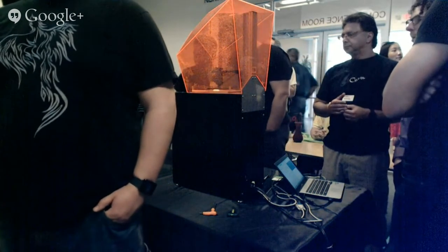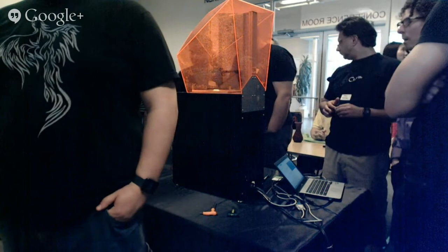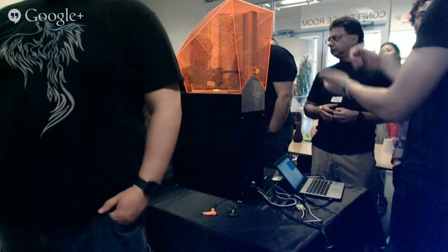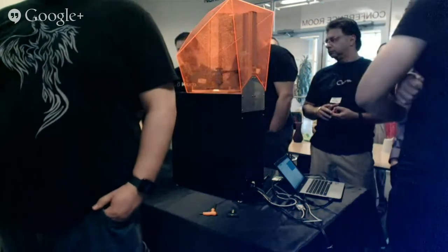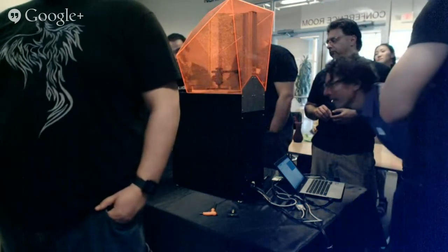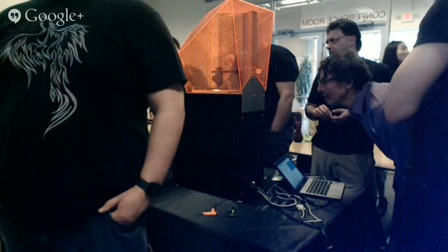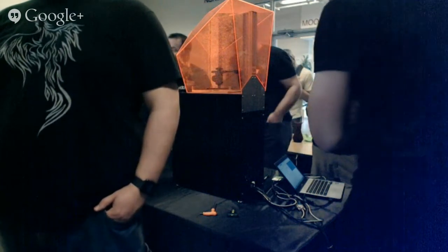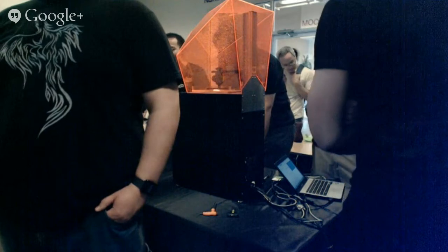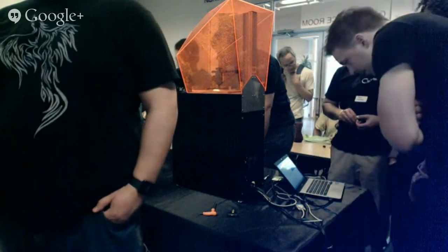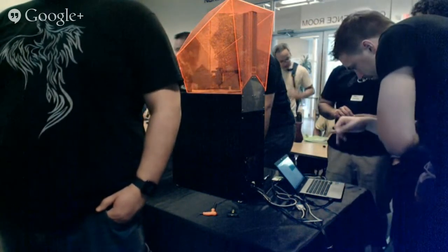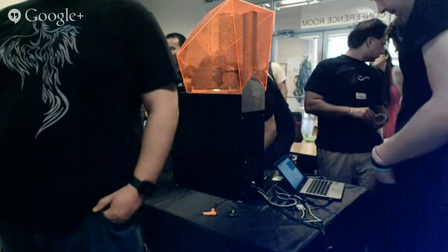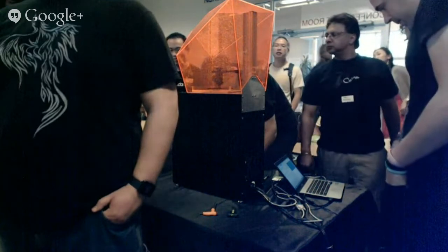It is a little weird. I've got a video on YouTube that shows the cleaning process. Dish soap doesn't clean resin the same way it does grease or oil in your dishes. It won't emulsify the resin. What you're really using is the surface tension effect of the detergent, and it causes the resin to bead up much more easily than it would on just water.